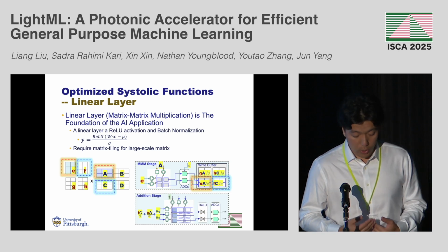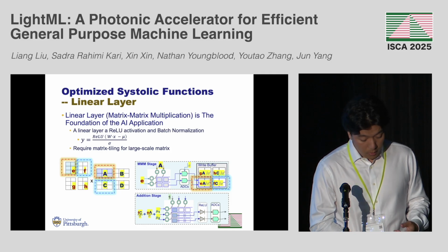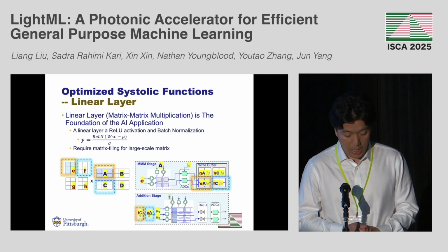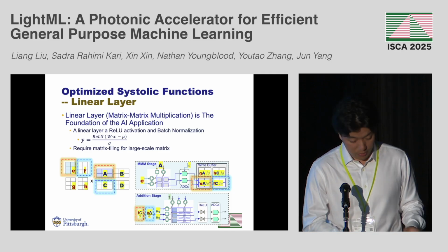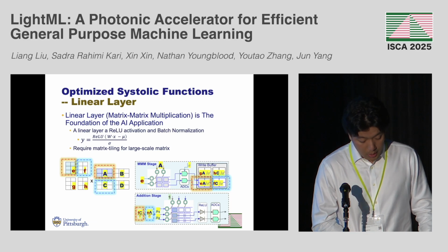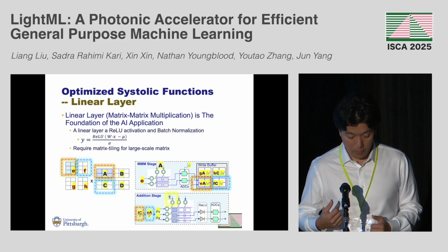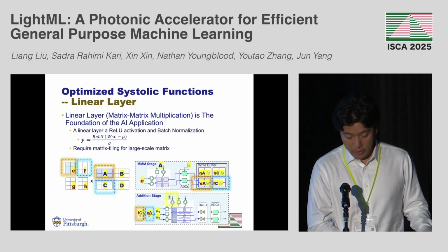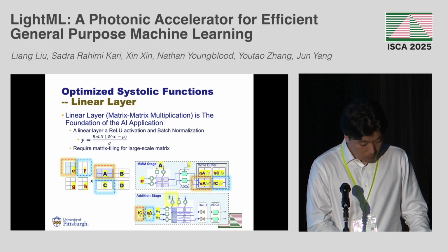So again, we utilize the crossbar to achieve the addition operation. We first read the elements that we want to add, and then feed them into the same direction of the crossbar device, coupled with a constant 1 signal in the other direction. Then the accumulated result will be in the capacitor, which is our summation output.